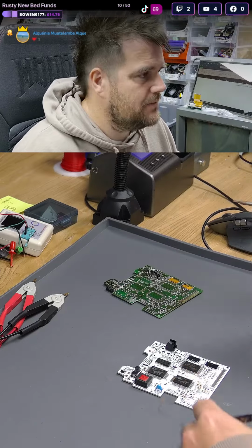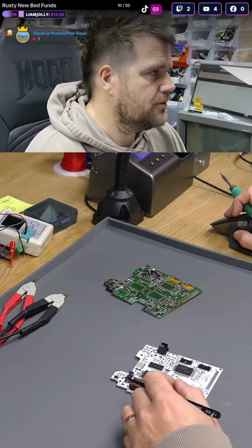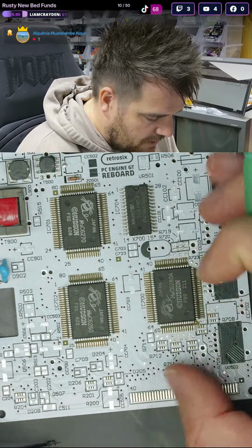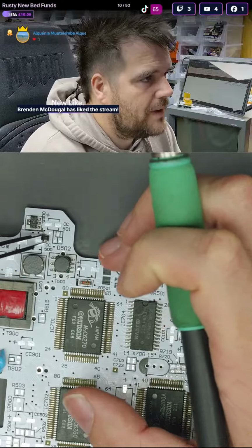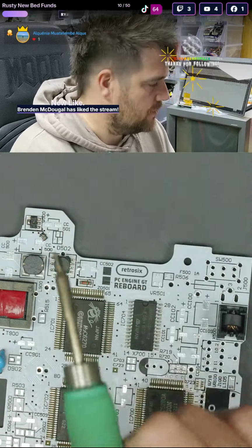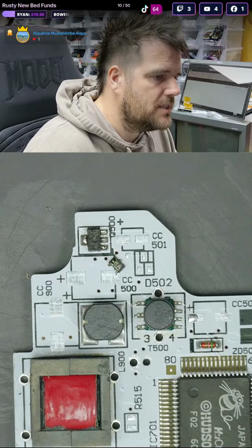It's about identifying the item, so you don't really need high quality internals. Buying a cheap component tester is probably as good as an expensive one for the most part, whereas buying a cheap LCR meter is nothing like buying a good one. So it's just about knowing where I want to spend my money and not waste it.